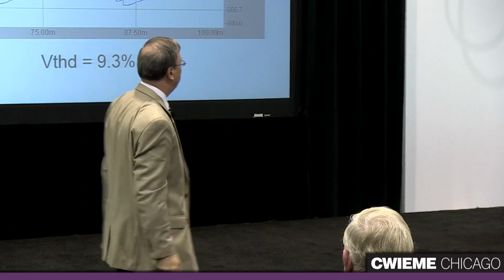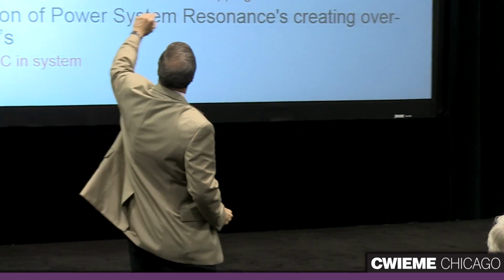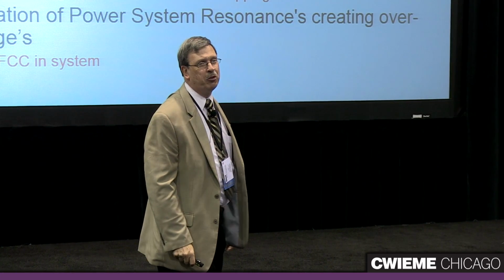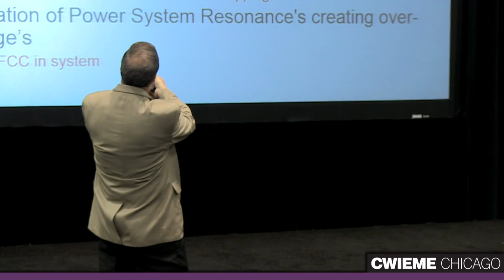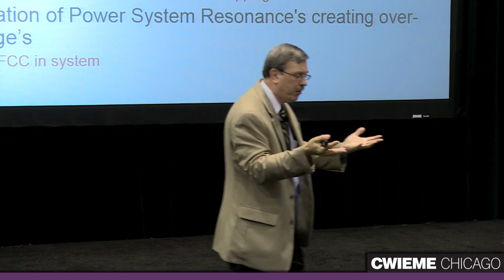So we call it flat topping. All right, so these are the types of problems that have come about with respect to harmonics. With respect to some of that current that's in those harmonics, the transformer has to supply those currents. That means instead of supplying just 70 amps of fundamental current, it has to supply 77 amps, 10% more current, simply because you've got those harmonics in there. And not only that, but those harmonics are higher frequency, so that means there's more eddy current losses in the transformer, which means more losses in the transformer because of that.